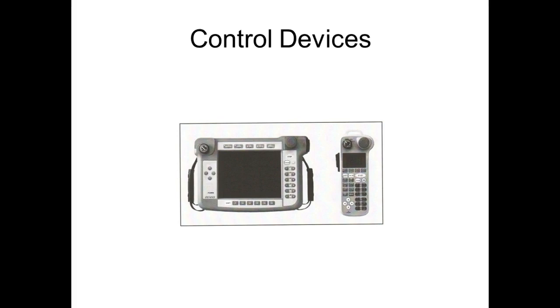So if I go over there and write my program using this teach pendant, then that is what we call online programming. And you're right, PLCs are predominantly offline programs. What's nice about a PLC is I can write a PLC program and not even hook it up to a PLC. A lot of times you can't do a lot of programming, but most of the time you can do minor modifications on a PLC while it's online. So if you wanted to change the time of the timer, a lot of times you can do that. And you can do the same with a PLC. I can take a program that's in the PLC and download it into my computer with an application. You can't do that on everything.